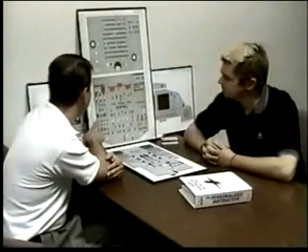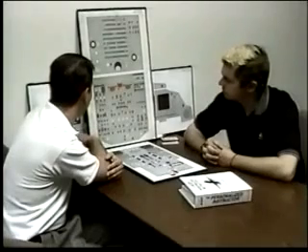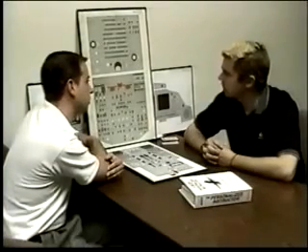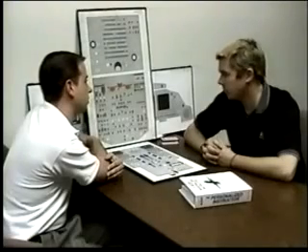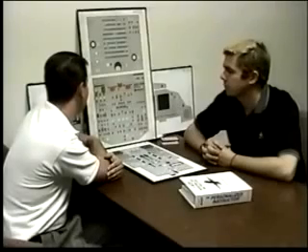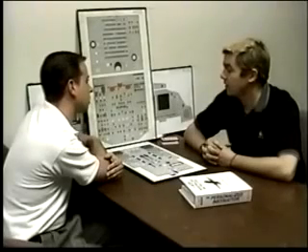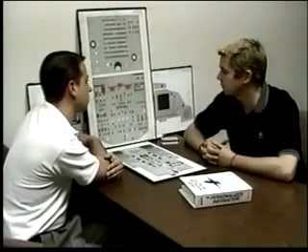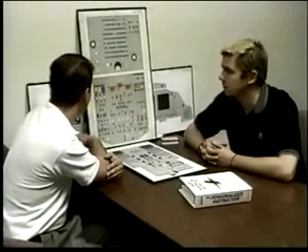Well, assuming that generator 1 is now only powering the fuel pumps in the left and right, what will generator 2 do? Generator 2, without selecting the bus tie off, is going to power AC bus 1 and 2. And what are we setting ourselves up for? We're basically isolating ourselves with the avionic smoke configuration. We're going to isolate the system here.